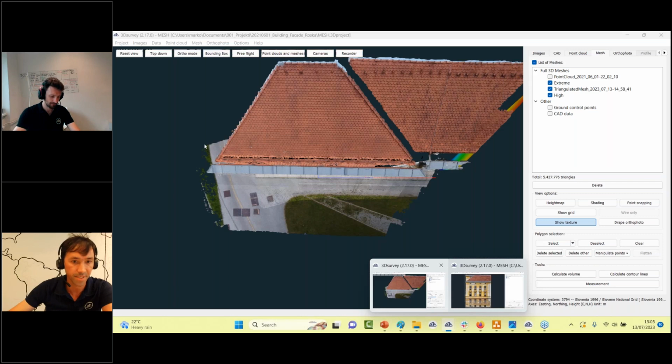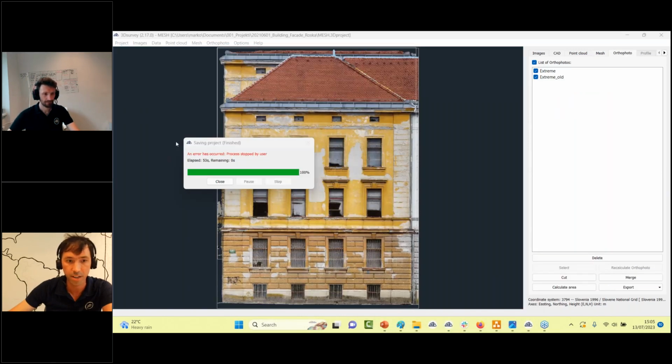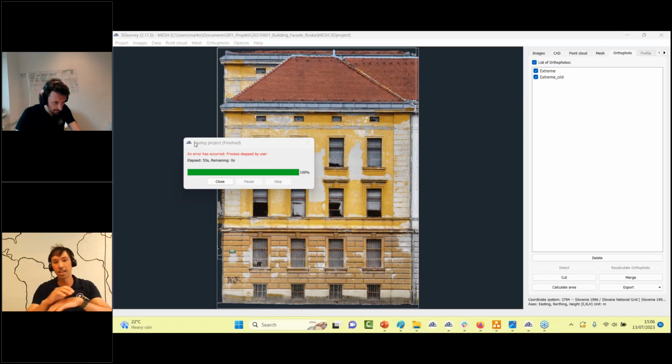Okay, then another question here. How do you transform the coordinates from UTM coordinates to Gauss-Krüger coordinates? Okay, really good question. Also, this transform tool, which Matthias shows you how to use to combine two data sets, could help you to do this. You just need to import identical points from UTM and identical points from Gauss-Krüger, and this should